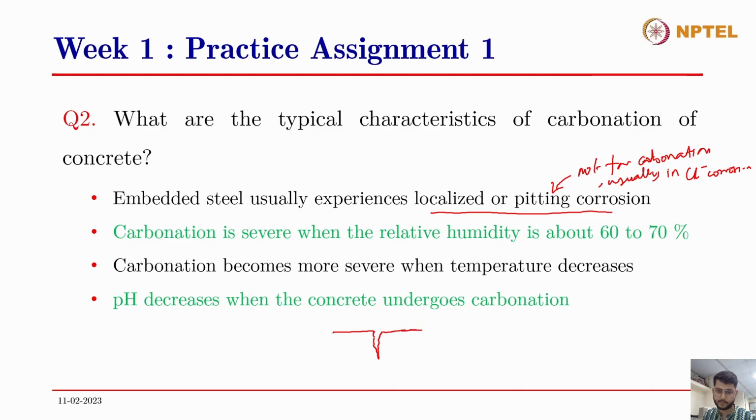But suppose this is a concrete surface, and this is another concrete surface. I mean, this is a concrete surface with a surface crack on it. Then if there is a presence of a crack, the carbonation can be rather localized. Let's say this is a cross section of a concrete element. The carbonation in this would be kind of uniform all around. The carbonation depth will be uniform all around, right? But if we compare it to a cracked concrete, the carbonation would be more localized.